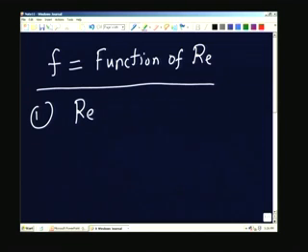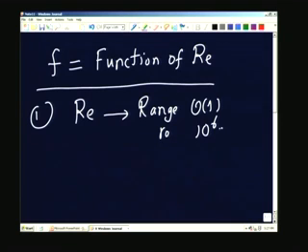That means it can be any value. It can be without flow. If the flow velocity is 0, Reynolds number is of course 0. If the flow velocity is very high, the Reynolds number can be very large. In other words, Reynolds number range is very large. Let us put it as order 1 to maybe 10 to the power of 6 or even higher, it depends on the particular occasion. Of course, the friction factor is normally a small quantity.